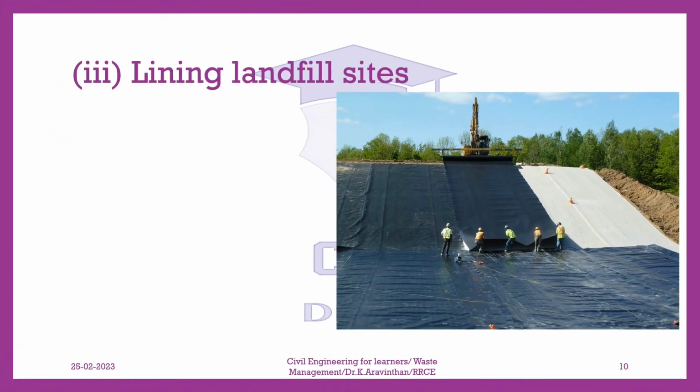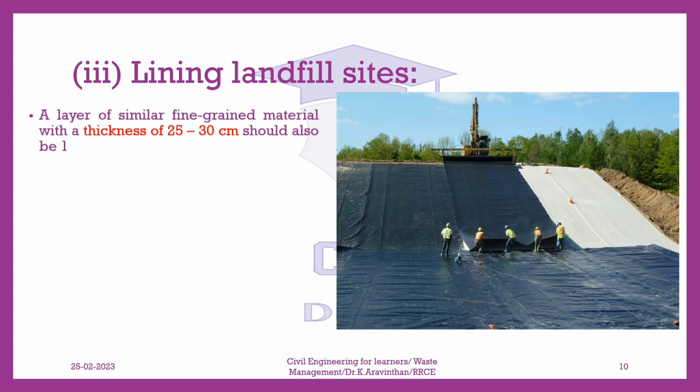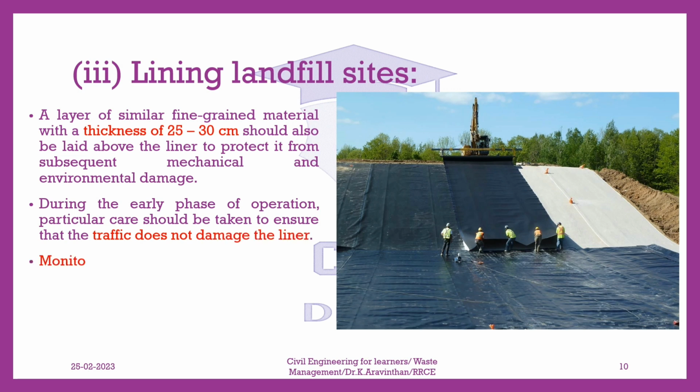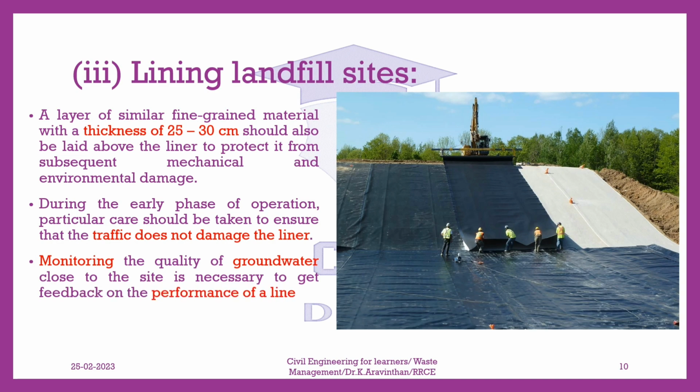3. Lining landfill sites. A layer of similar fine-grained material with a thickness of 25 to 30 centimeters should also be laid above the liner to protect it from subsequent mechanical and environmental damage. During the early phase of operation, particular care should be taken to ensure that the traffic does not damage the liner. Monitoring the quality of groundwater close to the site is necessary to get feedback on the performance of a liner.